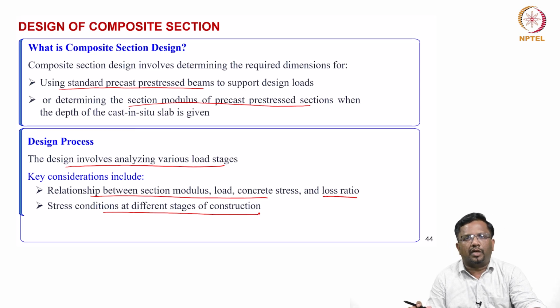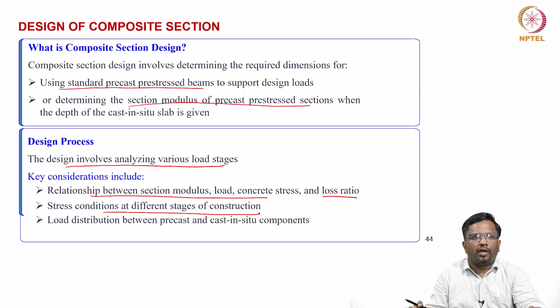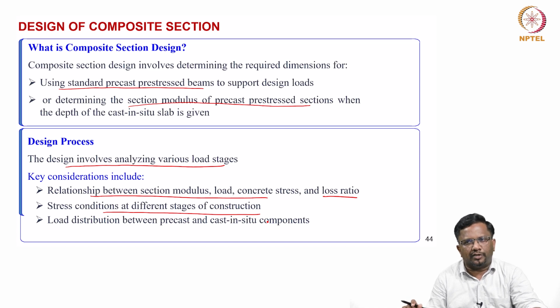Then for the live load moment, it doesn't matter whether it is propped or unpropped. The entire composite section, we have seen, will be resisting the applied moment. And then the load distribution between the precast and cast in situ components. We have also done the stress analysis in the previous part.